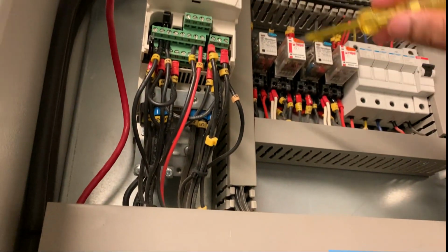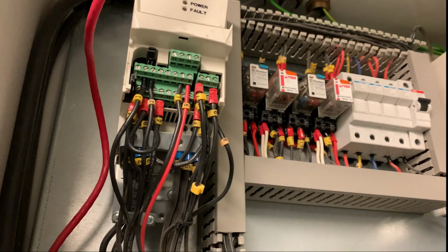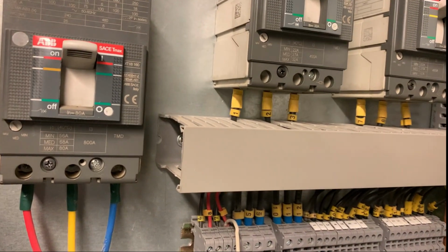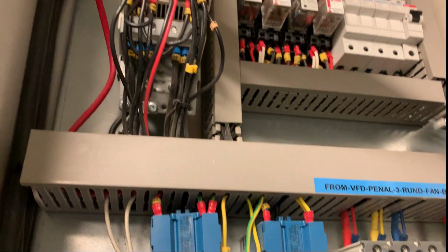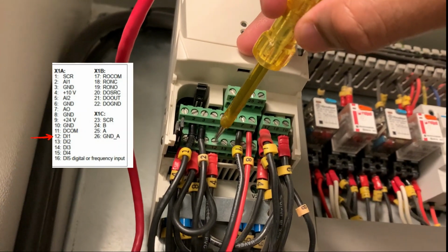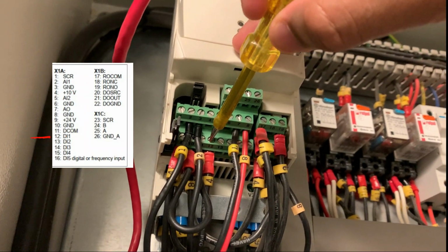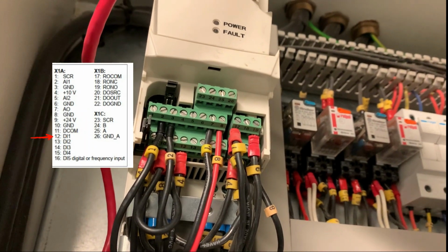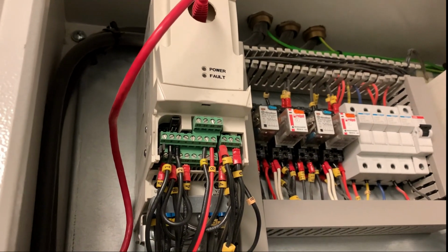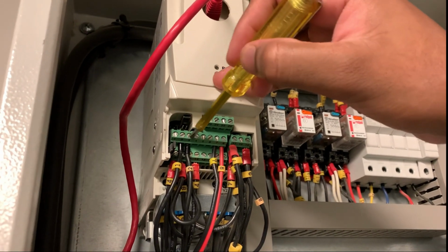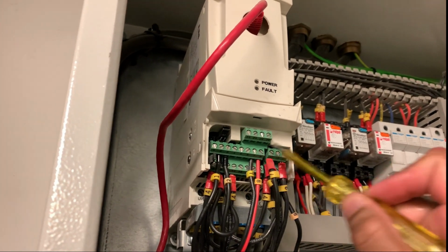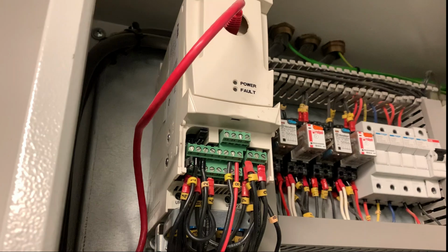But once there is a fire in the building, it will automatically get triggered, and once terminal 4 has 24 volts, it will turn on this VFD. Terminal 4 is connected to the multi-functional input, that is digital input 1. So when there is 24 volts on pin 12, our VFD will run. Through pins 2 and 3, we can increase or decrease the speed, and we will see the feedback from pins 7 and 8. And there are 2 relays, one for run status and one for trip status.